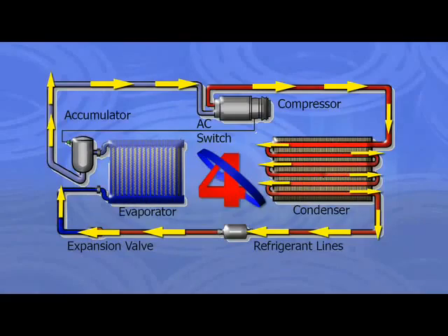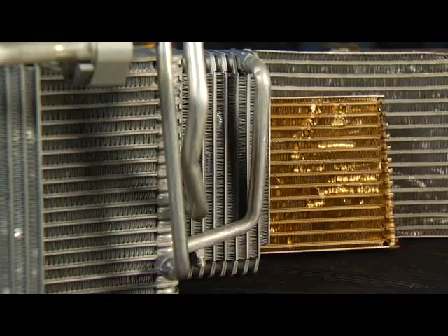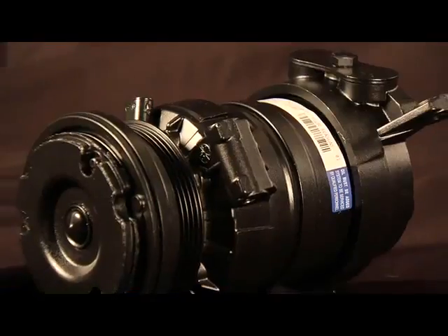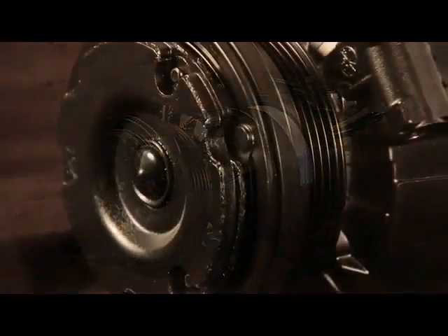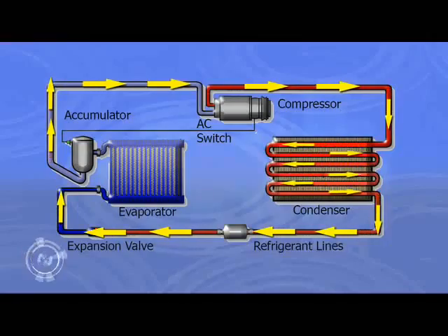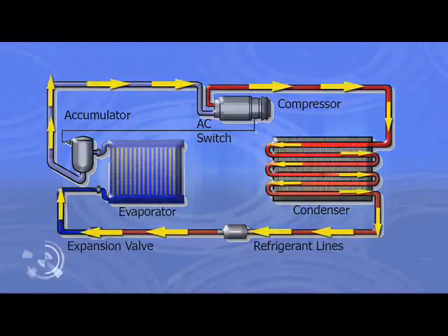A clean AC system is a key factor when guaranteeing the durability of your AC repair jobs. Some components can be successfully cleaned of contamination, and other components must be replaced. The end result must be a system free of any contamination that could destroy the replacement compressor, restrict the flow of refrigerant, or inhibit the heat transfer process.